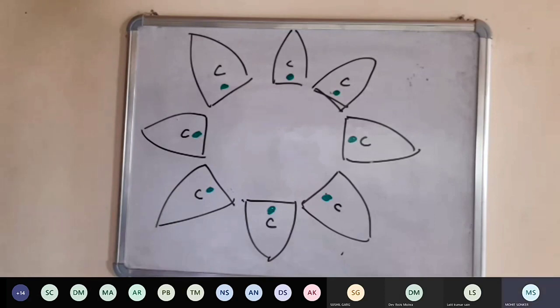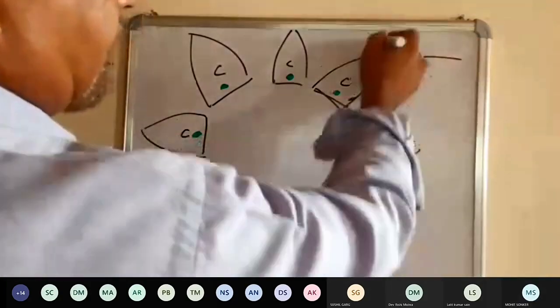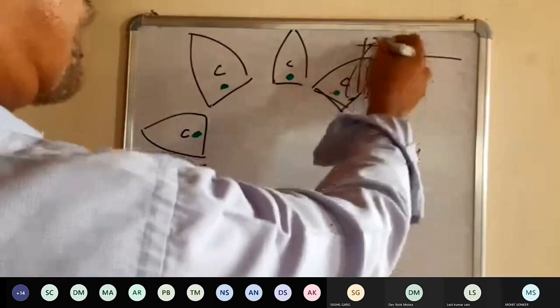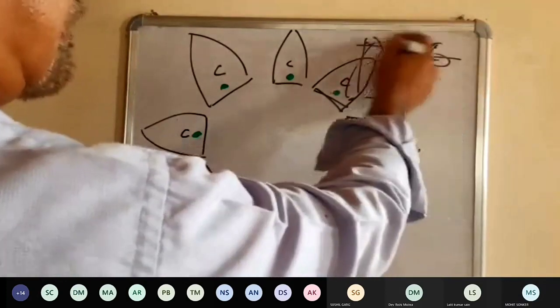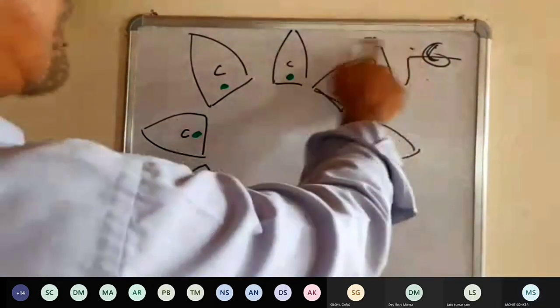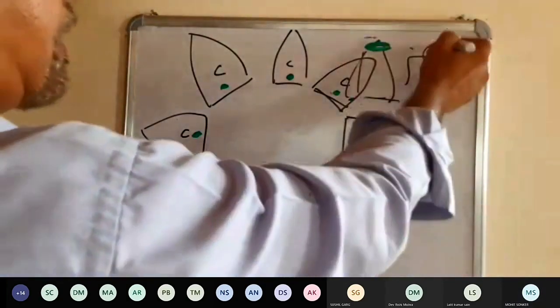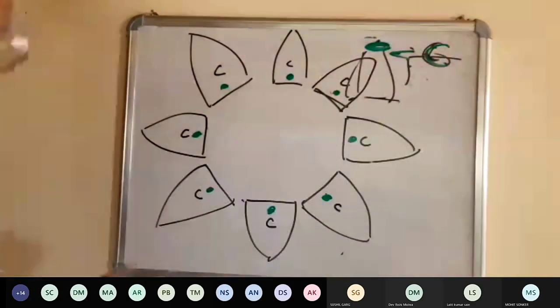Almost level with the compass. Yes, sir. The funnel near the monkey island is like this, so the part of the funnel is near the compass, which is aft of this. Yes, sir. So if we are saying that this is getting to blue pole, this here is becoming blue pole. So blue pole aft of the compass. Is that correct? Yes, sir.